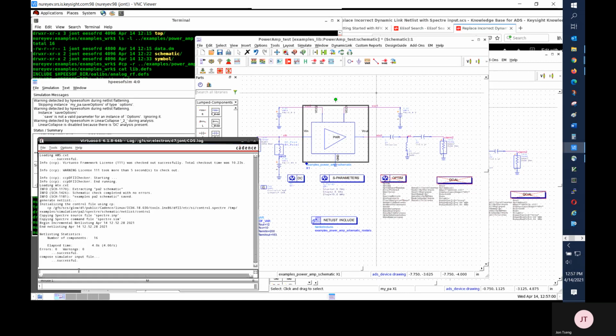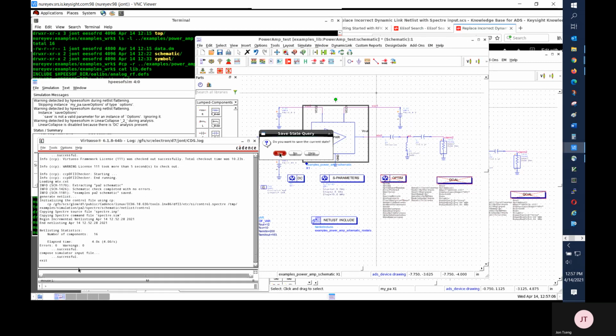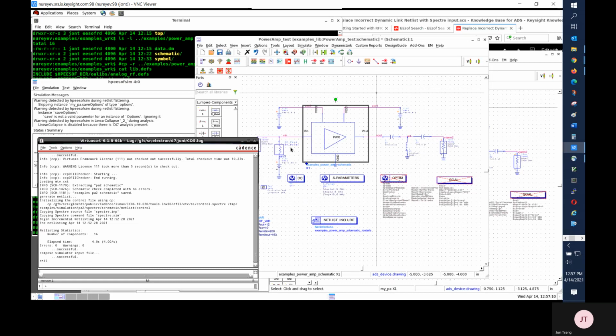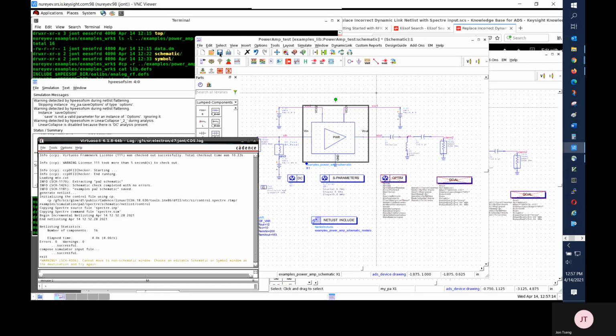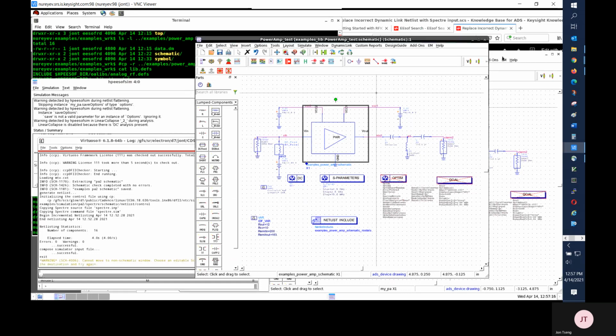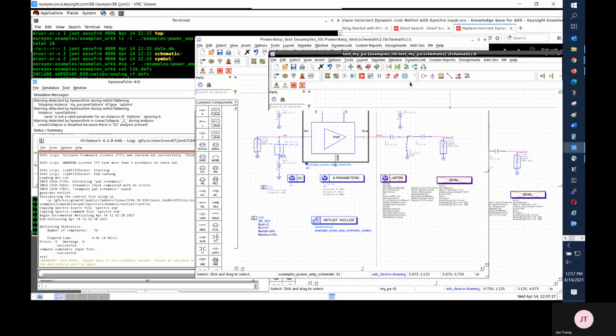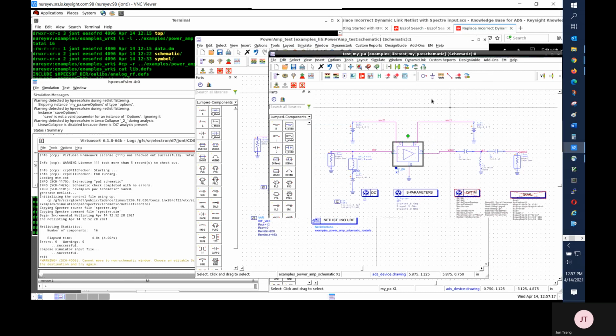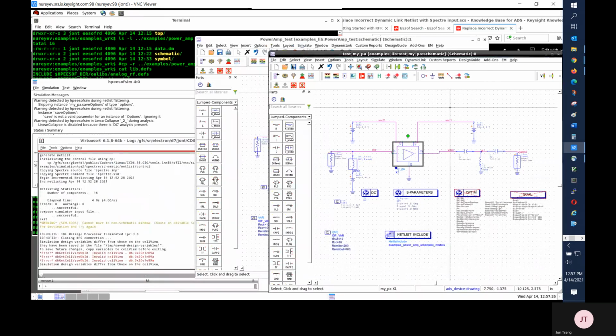I could have run these simulations in ADS standalone, but I kept Cadence up because I wanted to generate the Spectre netlist file from ADE. You typically don't need to do that, since most people usually run simulations in Spectre before trying to run ADS simulation with ADS designs. So Spectre input.scs should already exist under Spectre's simulation directory.